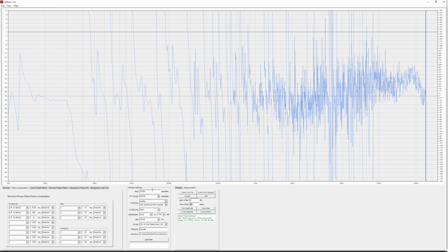It's not a straightforward process to find the correct phase correction parameters, especially in multi-way and multi-port designs with high filter orders like these Kantas. You will need accurately time-aligned impulse responses of your speakers, and especially for the box filters, you might need near-field measurements. I have explained methods for most of these in my previous tutorials, so I will not go into these details in this one.